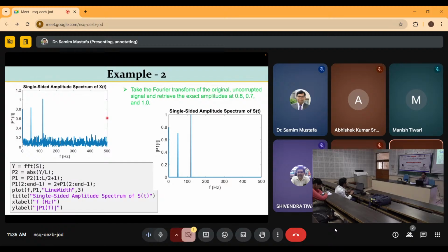Every system, even us, if you model me using my entire stiffness and mass matrix, assembling all the parts and then modeling, you will see I have a certain frequency. Some other person has a different frequency. Some other object has a different frequency. Every object has a defined configuration and defined material properties, so it has a defined natural frequency, which is fundamental to that object, at which it vibrates, right?